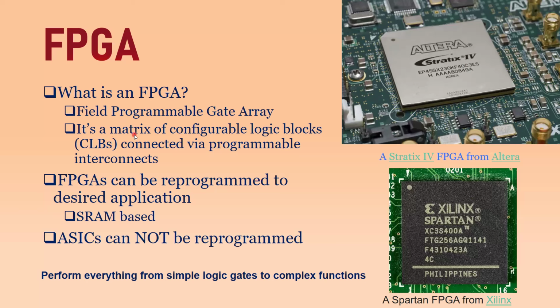Inside it, you can say that an FPGA is a matrix of configurable logic blocks, in short form CLB. Those logic blocks, as I said before, can be reconfigured again and again, and they are connected via programmable interconnects. So it's a kind of switching function. You can connect logic functions to each other to realize bigger and bigger logic functions. So FPGAs can be reprogrammed to the desired application. Any application that you want to implement, you can have it configured inside this IC, and then you can use it for some specific field in medical, avionics, instrumentation, industry, etc.